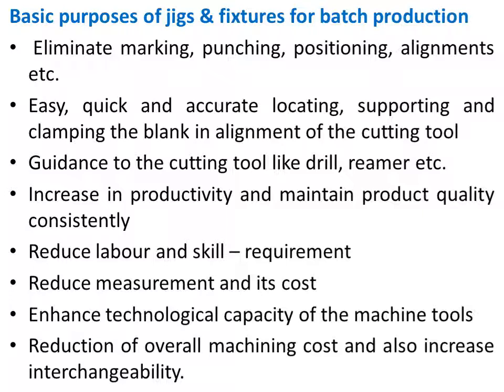The fourth point is increase in productivity and maintaining product quality consistently, because you are going to use the same fixture for n number of components. You are transferring the same accuracy to all the n parts without any change. So you will be able to maintain the product quality in a very consistent manner.